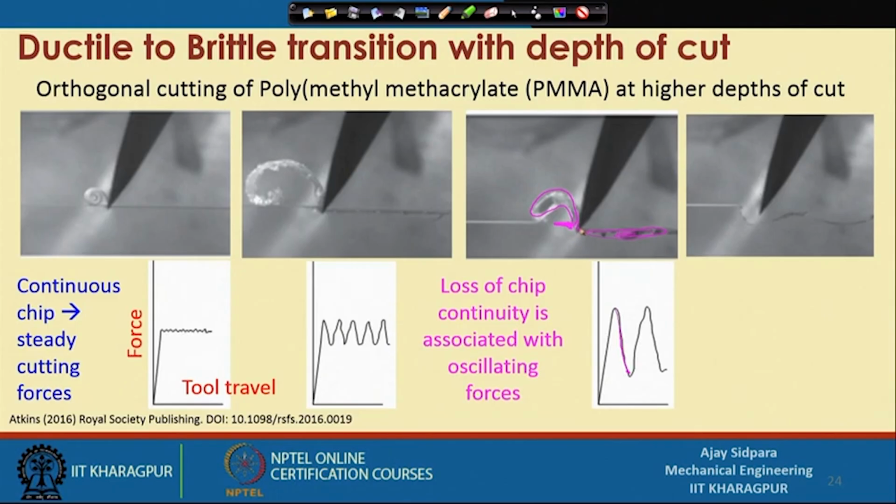So, when the tool reaches that location, it does not require so much force. So, it removes this much amount of material. Now again the fresh material is coming, so again you need a very large amount of force, and that large force is again coupled with the loose material in this case. So, you are getting a very high fluctuation during cutting at a high depth of cut.